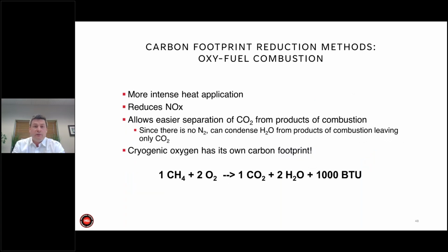Other things you can do is oxy-fuel combustion. Instead of using air for combustion, use oxygen, and you'll be able to get more intense heat, and you'll be able to emit less NOx for sure. It also makes carbon sequestration and separation easier, because if you can find a way to get water out of the system, all you have left is carbon dioxide, and you don't have all the nitrogen that you have to pump out of the way too. So that's actually a benefit of oxy-fuel combustion if you can do it.